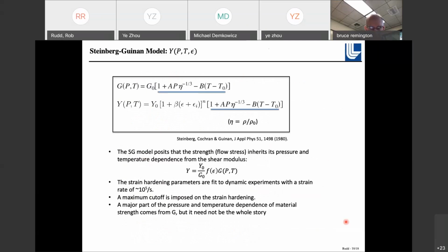So the thing that's different here from the previous lectures is that these experiments are typically done at very high pressures, pressures that are comparable to the pressures at the core of the Earth. So say, a megabar to several megabars of pressure, where 1 megabar is 100 GPa. So these are quite large pressures, and accounting for pressure hardening is important. Pressure does typically induce hardening in materials: the bond strength is getting larger as the material is compressed, and so you get a strengthening as the pressure is increased.